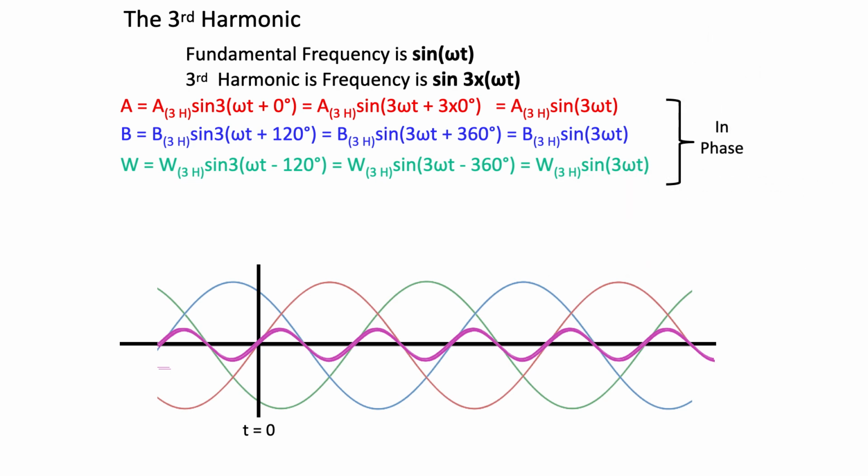This leads to the solution of connecting a transformer in a delta configuration, and sometimes it is done with a third set of windings in a transformer, called a tertiary winding, that is connected in a delta configuration.